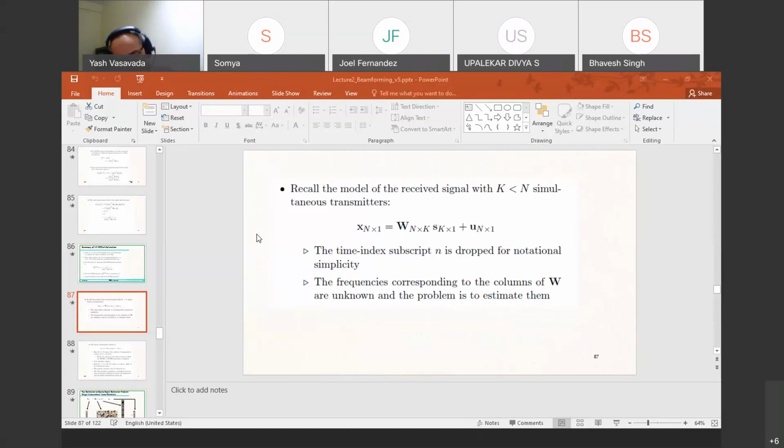And also the underlying property says that the overall dimension of the space which the total combined signal, the actual signal of interest plus the noise, occupies is the summation of the dimension of the signal subspace and the dimension of the noise subspace. So those are some of the underlying concepts that have driven the MUSIC algorithm.